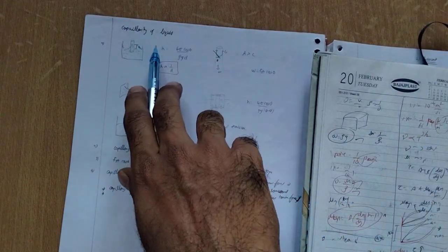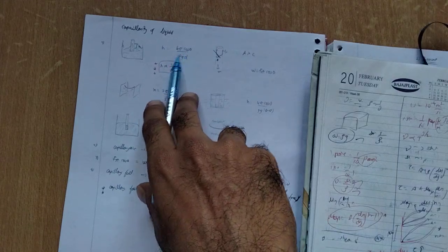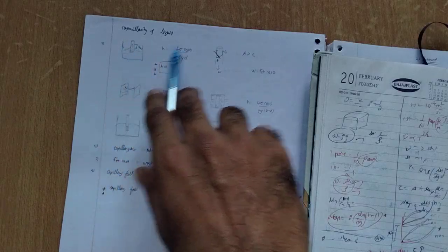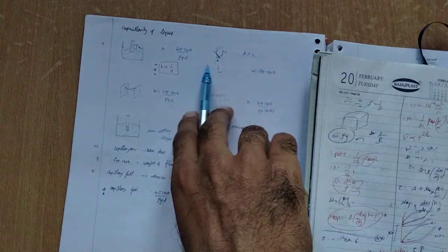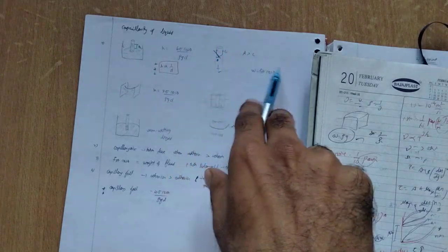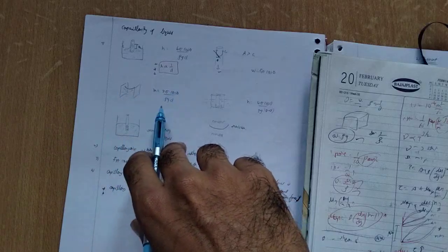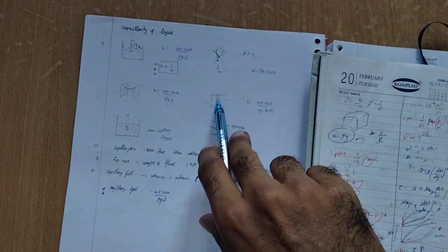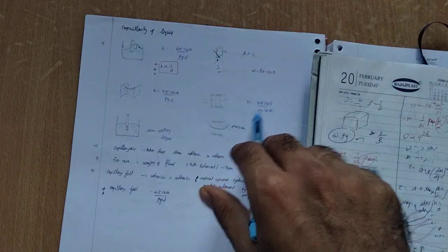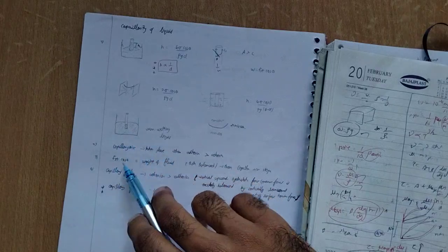Next one, capillarity of liquid. Capillary rise h equals 4 sigma cos theta divided by rho g d. So generally h is inversely proportional to the diameter of the capillary. Here the adhesion will always be greater than the cohesion. Just a simple thing: the surface tension force acts upwards, but the weight of the water acts downwards. So make sure they are equal and we will get the answer. For parallel plates, it is 2 sigma cos theta by rho g d. Generally a non-wetting liquid will have the meniscus like this, downwards. I think you can understand.